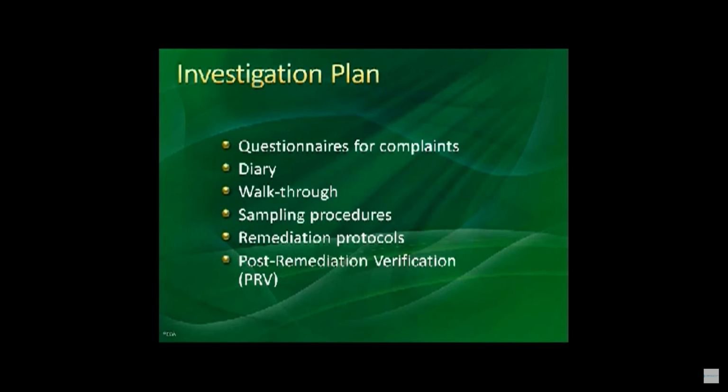The investigative plans that you might come up with are questionnaires for the complaints that are going on, and keeping a diary as you go through your walkthrough. You'll design sampling procedures. You may want to take on the responsibility of doing a remediation protocol. And always, in all of the work we've done in all of the hurricanes, a post-remediation verification.